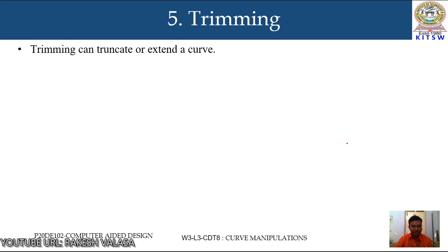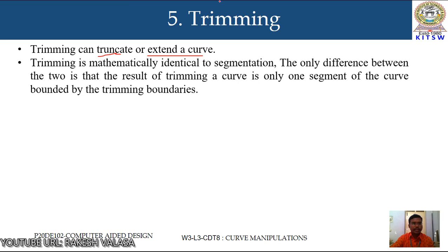Trimming curves or entities is a very useful function provided by all CAD/CAM systems. Trimming can truncate or extend a curve. Trimming is mathematically identical to segmentation.